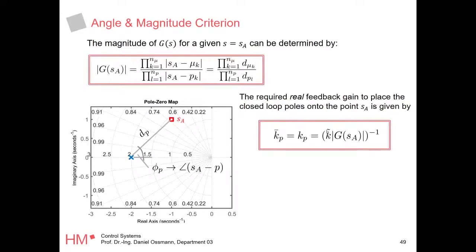And remember, when we have our system in the pole zero form, let me write down why this is the case. Let's say we have a system with S plus 1, S plus 2 in the denominator, S plus 10 as a zero, and we have 10 here. When you're drawing the pole zero map of this, real and imaginary, you take the first pole, minus 1. Take the second pole, minus 2. Then you take the zero, minus 10. You have the zero here.